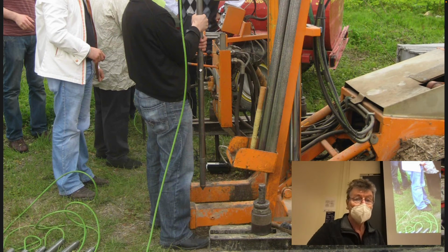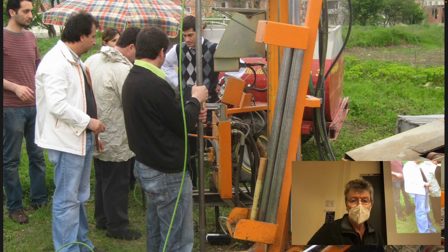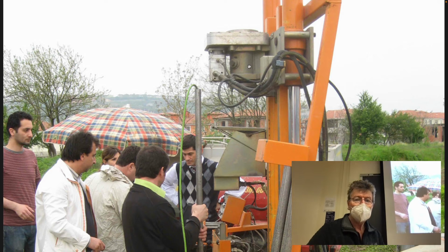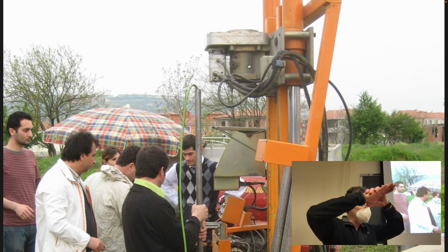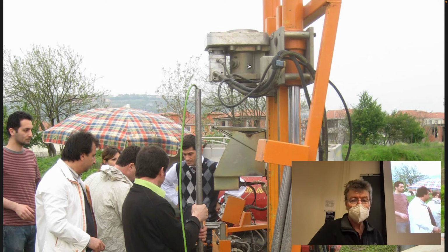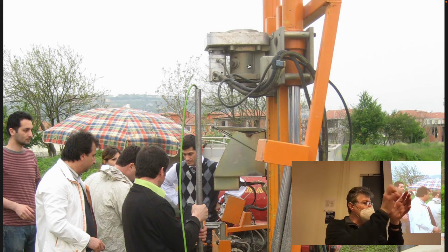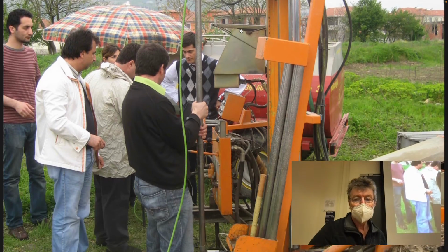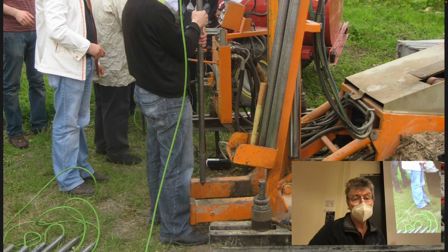This is the drill steel, looks like a meter tall. It's placed into this rig. This rig physically just pushes it into the ground at 2 centimeters a second. When it gets down to the bottom of travel, you've already added the next link on. This head then quickly comes up to the top, grabs the thing again, and keeps on going down. And so you can see you can move these inside buildings for contaminant hydrology type work, very transportable.